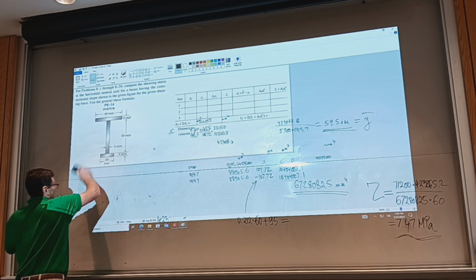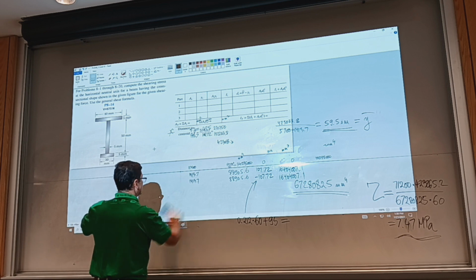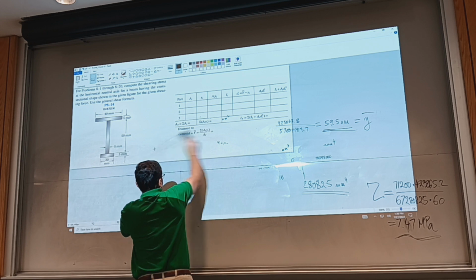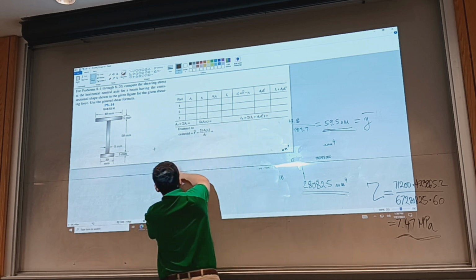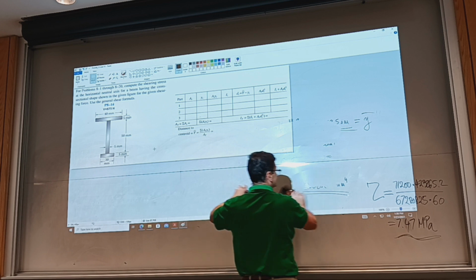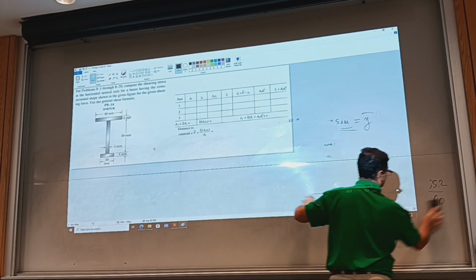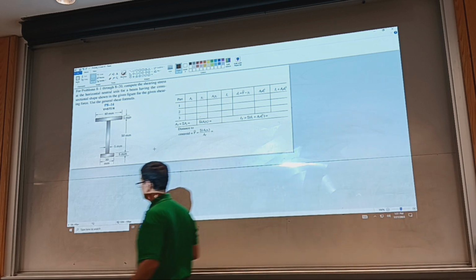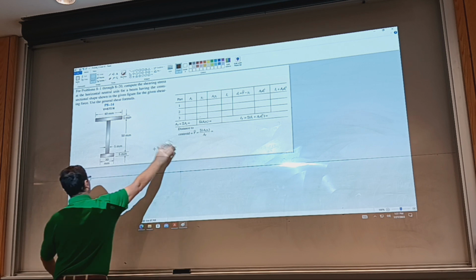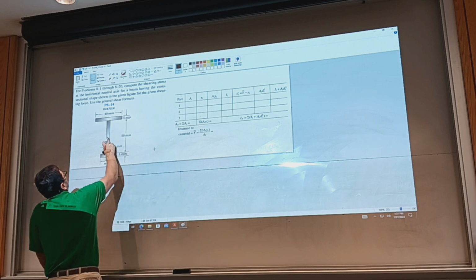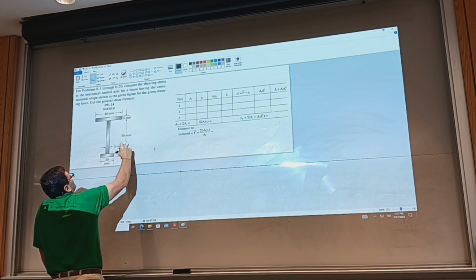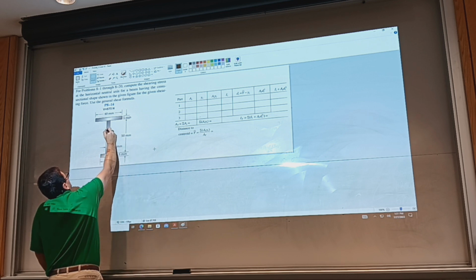All right, so this is an asymmetric T-section, and likewise, we need to evaluate the shear stress on the horizontal plane through the centroid. So for this full package, we need a table like this to find where the centroid is. It's not at the middle; it would be 30 millimeters from the base, further up.